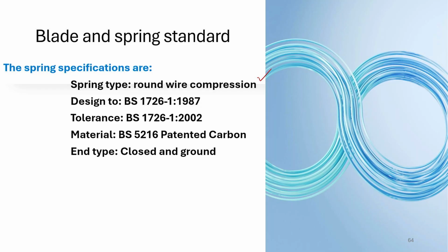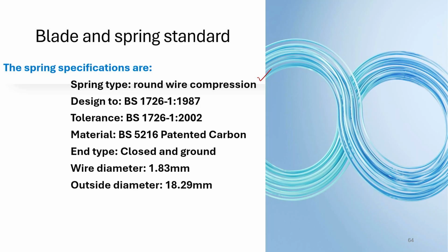A very specific spring was used here: wire diameter 1.83 millimeter, outside diameter 18.29 millimeter, spring rate, that is spring constant, 8.41 Newton per millimeter, and free length 12.23 millimeter.